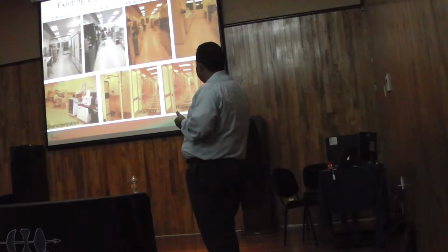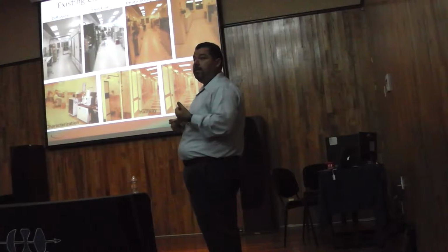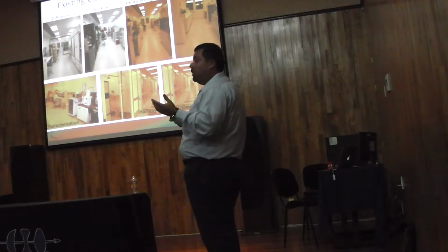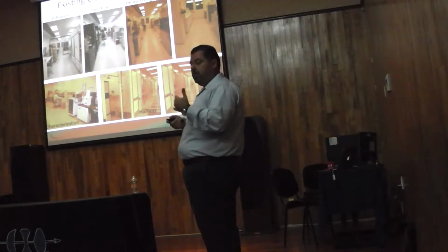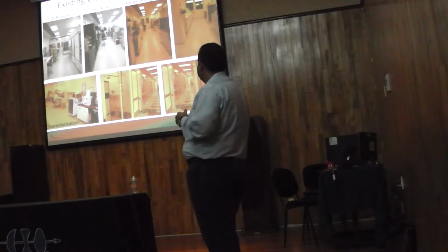We have the thin film deposition. And there we have sputtering systems, we have E-beam deposition system, and we also have, you may not see towards the end in there, etching systems. So we can deposit films, but we can also selectively remove some of those films as well.